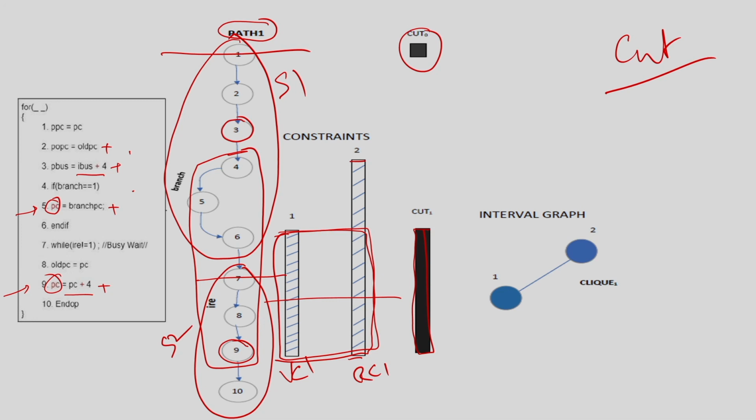Here the number of states gets significantly reduced, because my objective is to minimize it. I am going to do as much operation chaining and as much resource sharing as possible, with as many operations as possible executed in a time step as long as they do not violate my resource, timing and variable constraints.